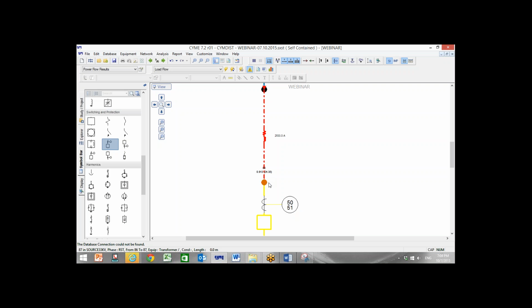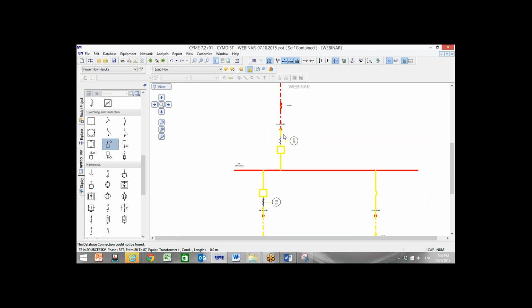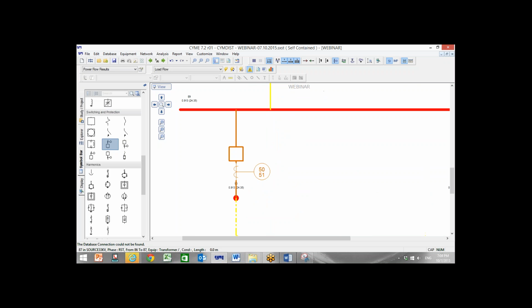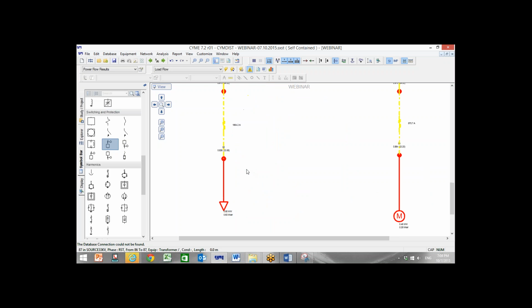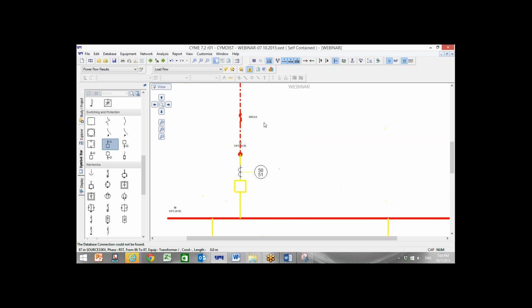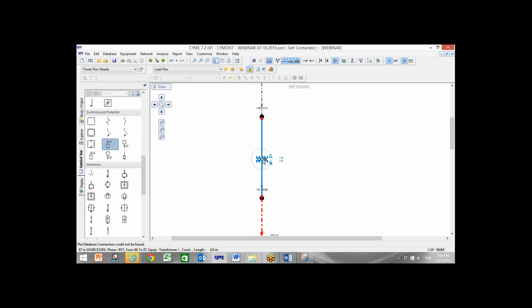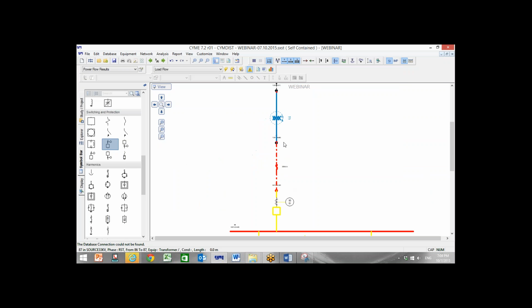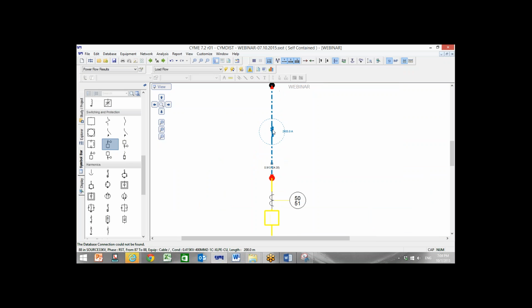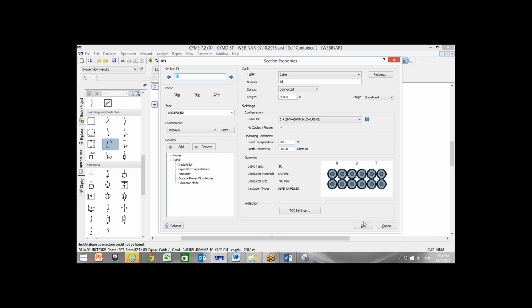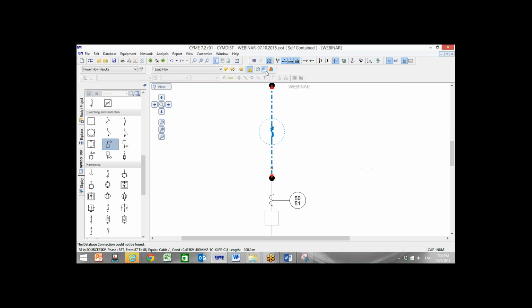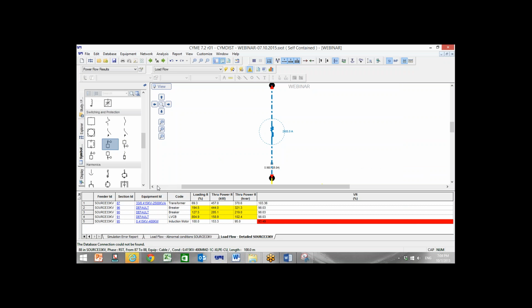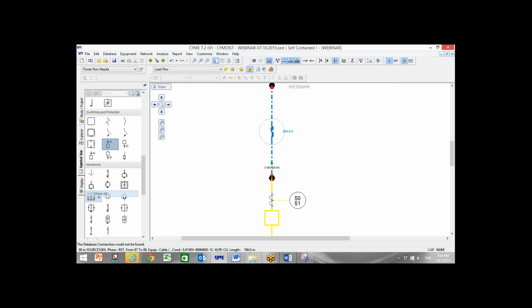So now the voltage here 0.91, and here 0.91, and you have under voltage here in whole network. How we can solve it? This transformer, maybe we can increase the voltage, not more than this. This is the maximum here. And this cable, most of the losses is on this cable. I think this 200 is too much for this cable. That's it. Okay, no problem.